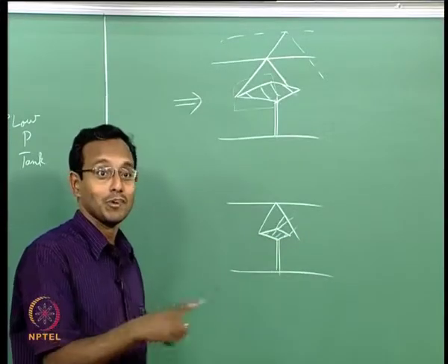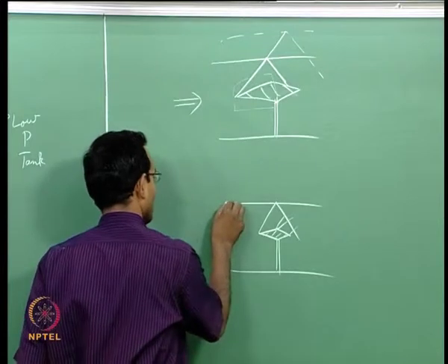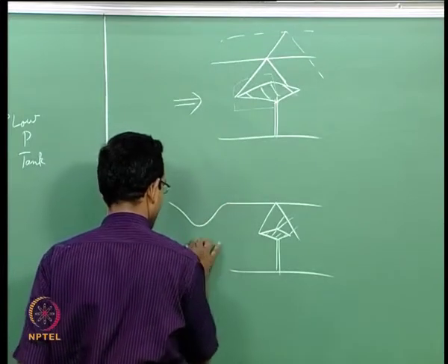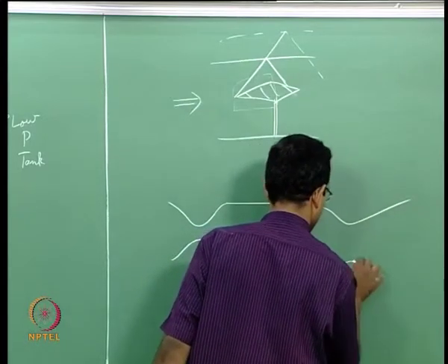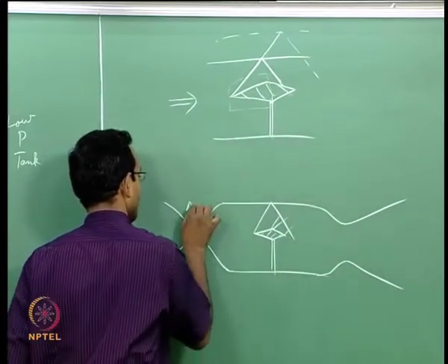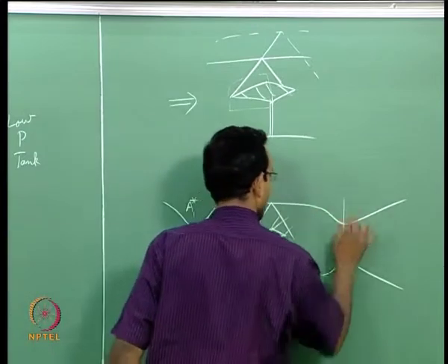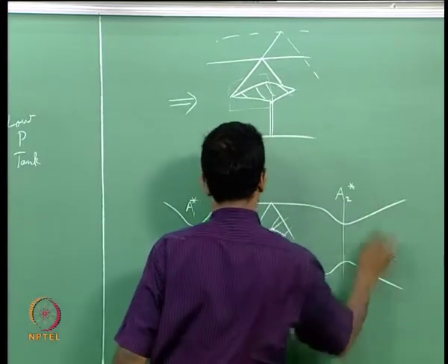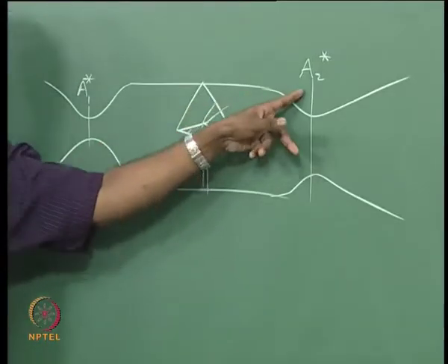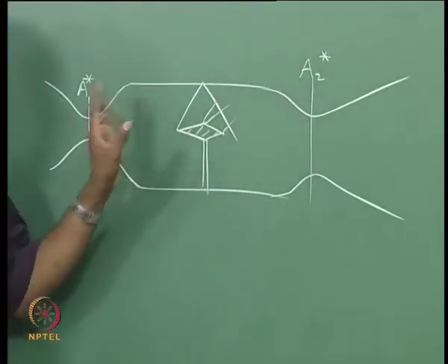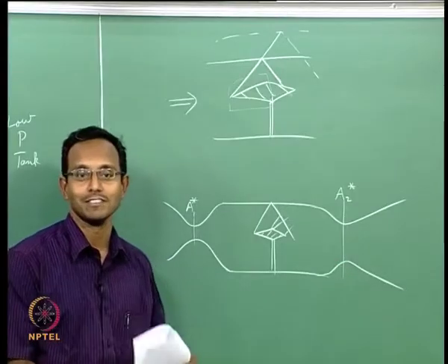The other thing we need to think about is, you know, typical supersonic tunnels have a nozzle and diffuser, and we said this is A1 star, this is A2 star, and we said that A2 star should be at minimum some value, if not the flow will not start, the tunnel will not start. What will happen?